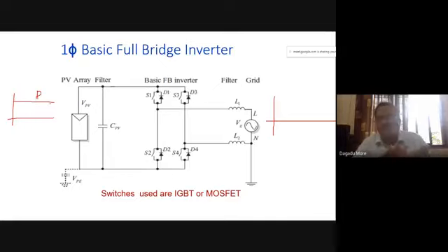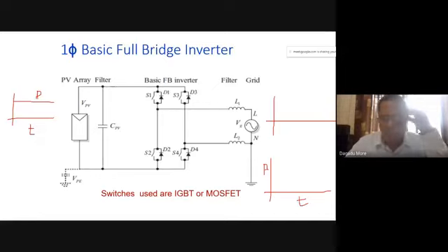In a three phase system, the power flow is constant. Is it right? If you go for three phase power, how does the total three phase power vary with respect to time, with balanced sinusoidal currents? Our x axis is the time. We are having a 3 kilowatt three phase load. Then how is the power with respect to time? The power will be constant in case of a three phase system.